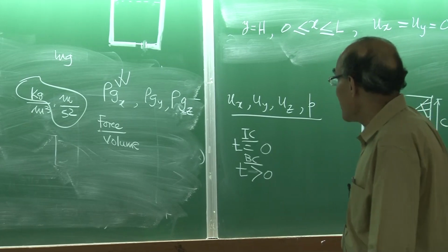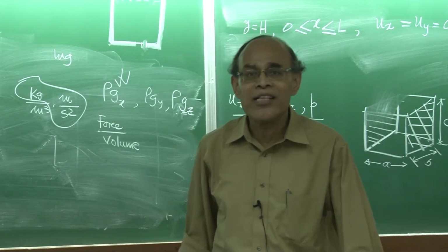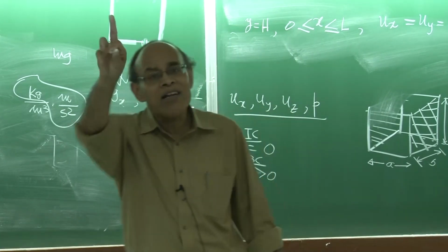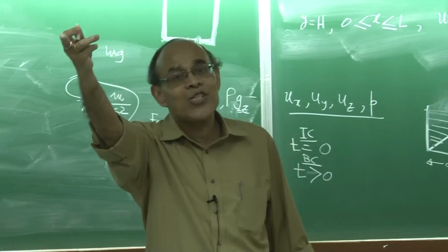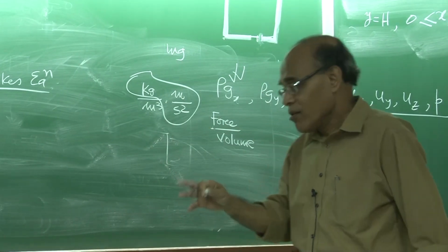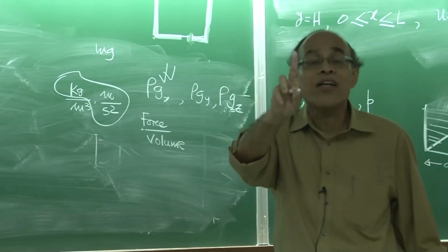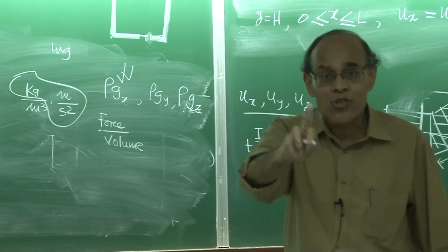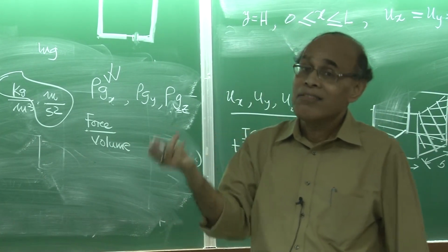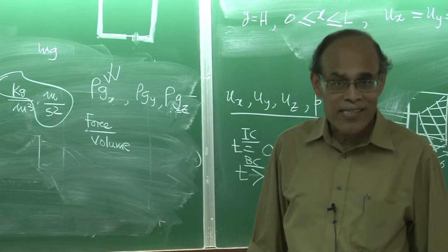So in your mind's eye, you should be able to see that, even though the equations are not on the blackboard. Imagine now that I divide all the terms in the momentum balance equation by rho gx, then the last term will be 1, because the last term was rho gx. I have divided all the terms. The last term is 1, which does not have any dimension. So applying the principle of dimensional homogeneity, all the terms in the equations have become dimensionless.